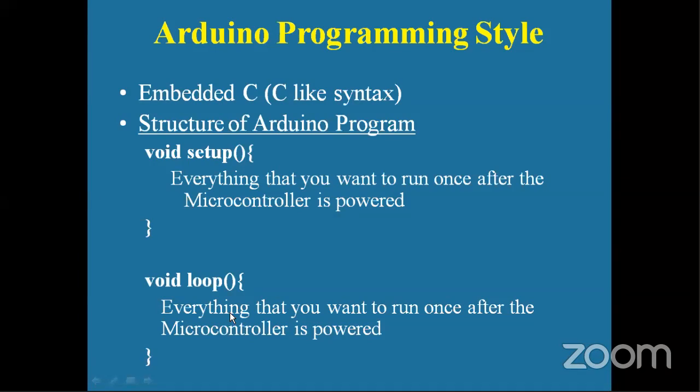And then whatever you want to execute continuously, as long as the microcontroller is kept on, we write into the loop function. Anything that you want to execute only once is in the setup function. Whatever you want to execute continuously, as long as the microcontroller is kept on, we put into the loop function. Two functions are there.